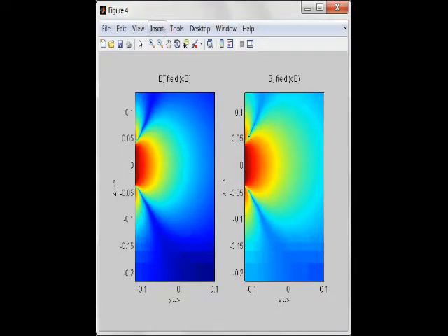In figure 4, we have the B1 plus and B1 minus field showing the XZ direction. We have two boundary conditions at approximately 0.05 and approximately negative 0.05. It is because we have excitation points and air gaps in the loop antenna. Therefore, we have some boundary conditions and breakups at the 0.05 and negative 0.05 positions.